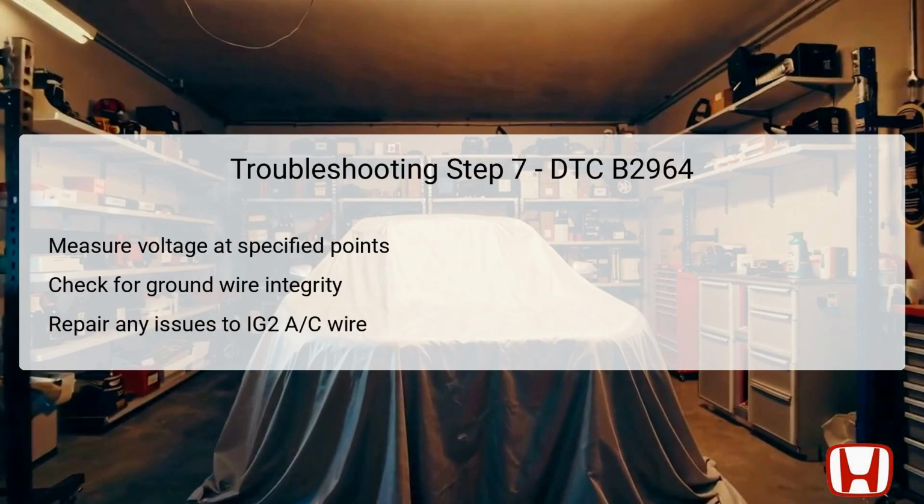In the final troubleshooting step, measure the voltage between two terminals while the vehicle is in the on mode with the climate control panel 20P connector disconnected. The test points are the identified female terminals, point number 19 on the climate control panel, and the body ground. Checking for battery voltage here helps confirm that power is being supplied correctly.